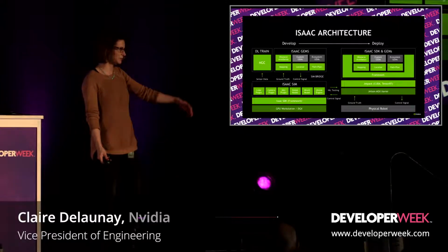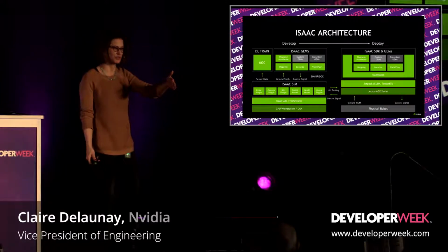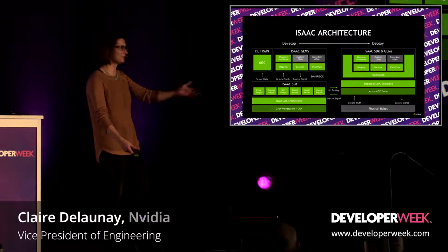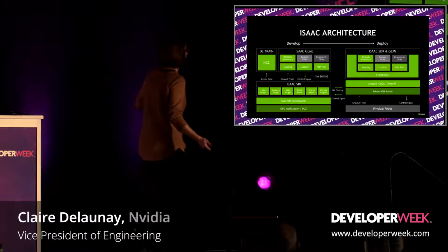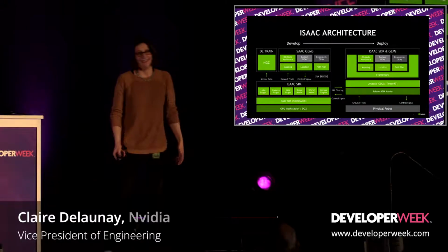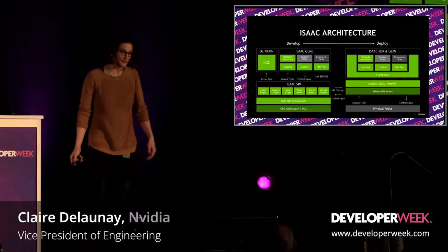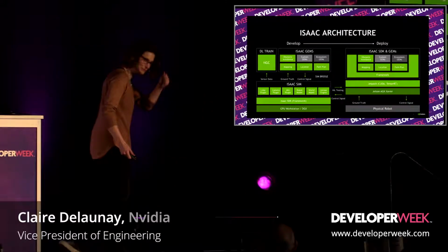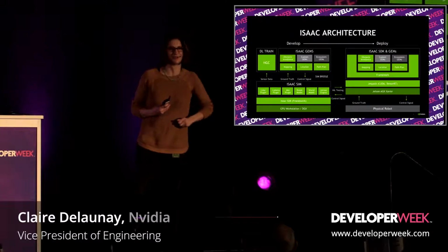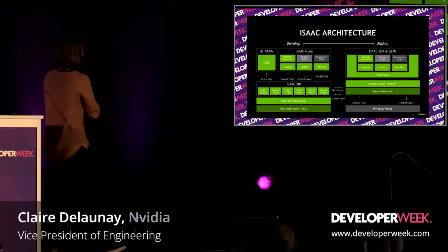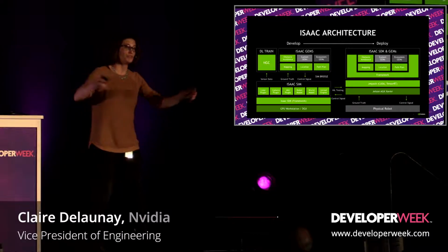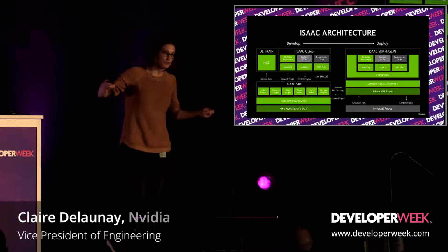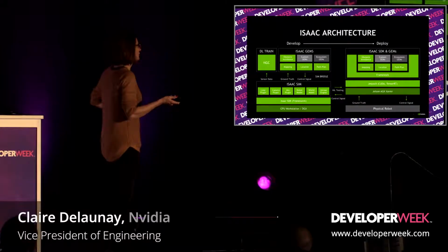USB decided to downgrade from USB 3 to USB 2, and as all your sensors were plugged into the same USB hub, nothing works anymore. Then it takes you forever to fix, because at the same time you uploaded your CL, and it turns out you changed something critical on the same component that was using this USB hub. And for robots, you multiply that by the number of sensors you have, because everything breaks all the time.